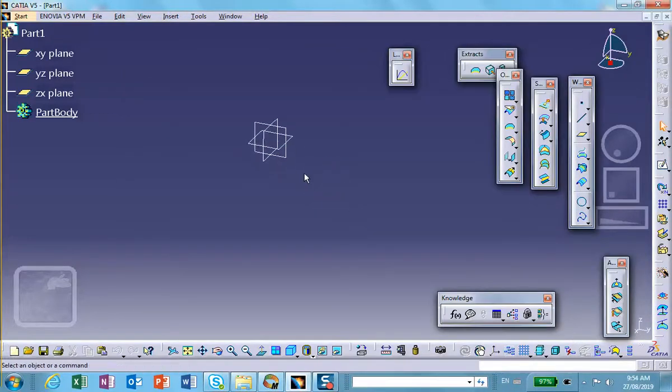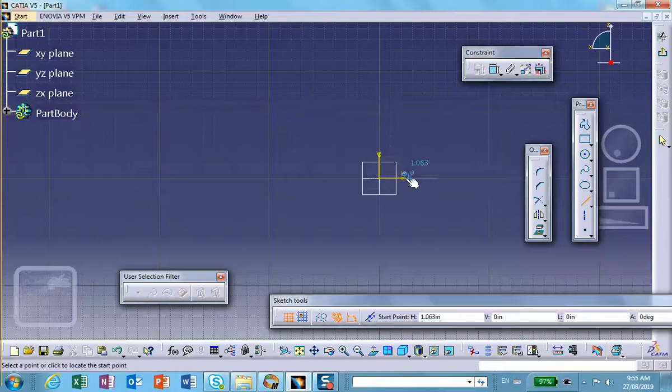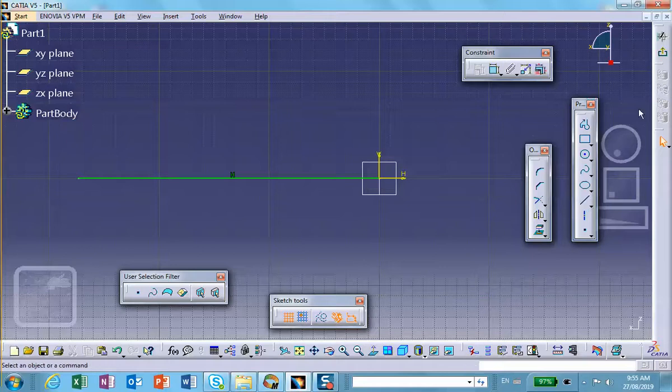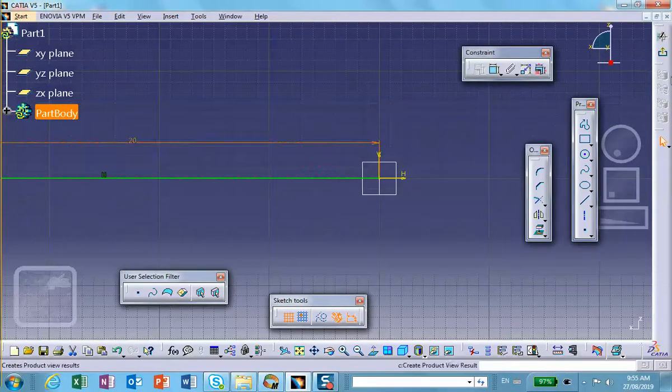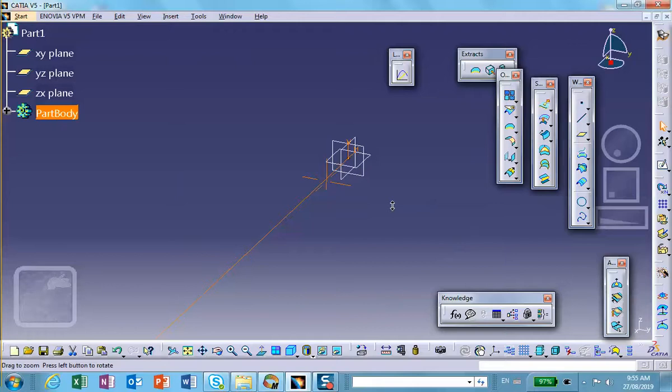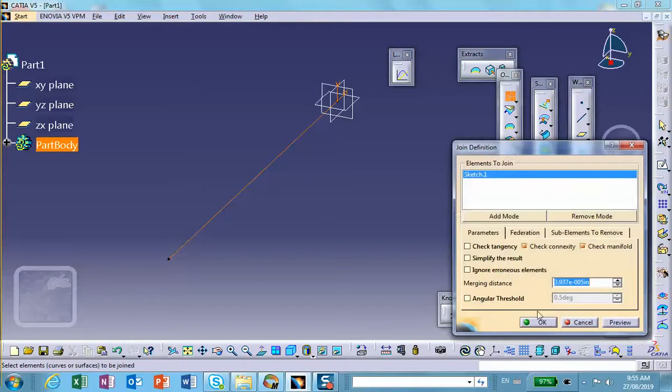So first thing that we're going to do is in a sketch we're going to draw a line, here on that vertical plane. I'm going to sketch, and all it is a line which is 20 inches long. Right there. Okay, let's make that thing 20 inches. Good, exit. Now, let us make sure that we join this thing. If we don't join this, later on when we try to mesh it with beam elements, it's not going to work. And very frequently when I do these video clips, I forget about that, then we realize that we have to go back and join it.